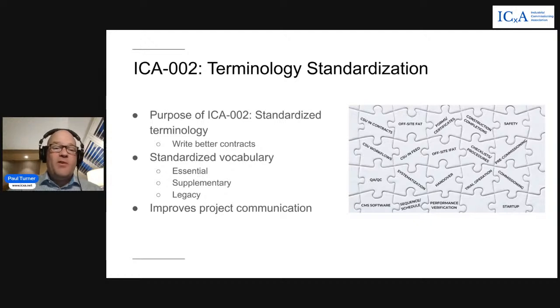For example, one of the terms is pre-commissioning. Everybody would think or know they understand what pre-commissioning means, but when I ask 10 people on a project what it means, I get 10 different answers. And I think for that reason, it's been very confusing for people to understand and agree on what is actually taking place before construction completion, what is taking place after construction completion, what is taking place during dynamic commissioning. The commissioning standard does not use the term pre-commissioning. We've dropped that completely.